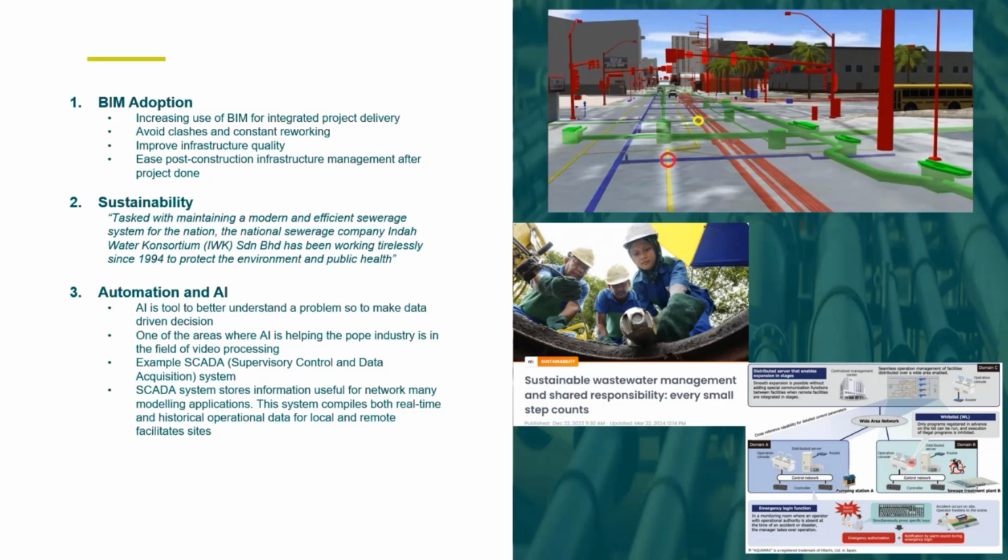When you model and design this piping in Civil3D, you can export or import into Navisworks, and you can do clash detection with the structure that you modeled in Revit, or depending on whatever discipline you want to check this piping against, maybe electrical, or maybe other utilities as well.